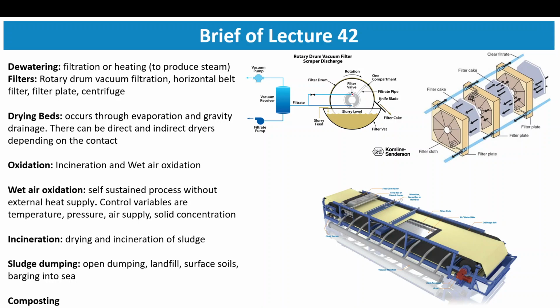Okay, so water will be able to pass through the filter while solid will not, right? So solid will be deposited on the outer layer of the filter, and some residence time will be maintained. That will result in accumulation of solid on the outer layer of the filter, which is known as filter cake, and water will be filtered.